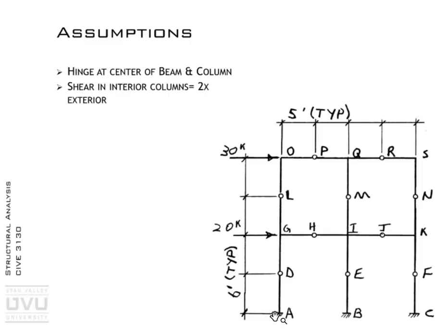So I can find the shear at the base. Then I can find the shear at the column, applying the same concept at a different location. And once I know that, I can start a free body diagram of each chunk, kind of like I do in a truss.